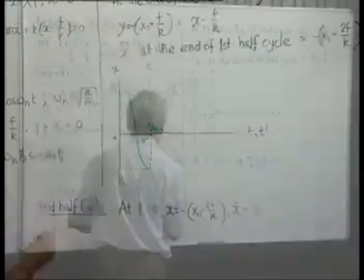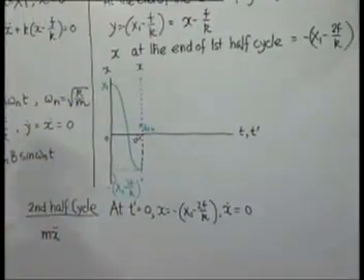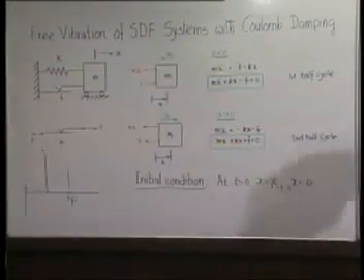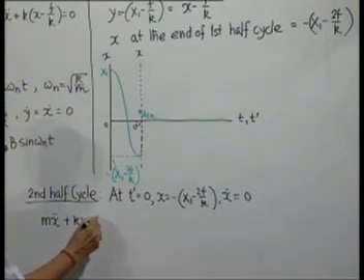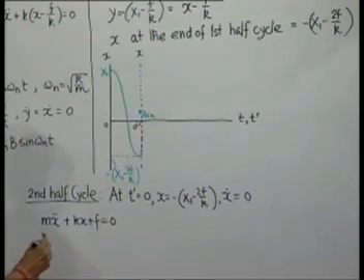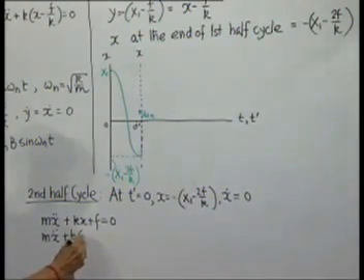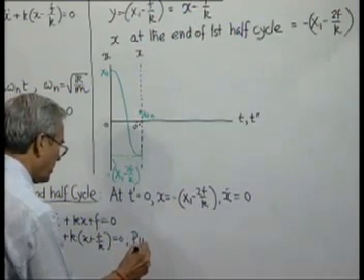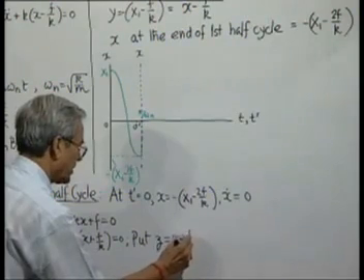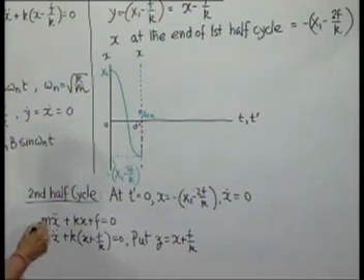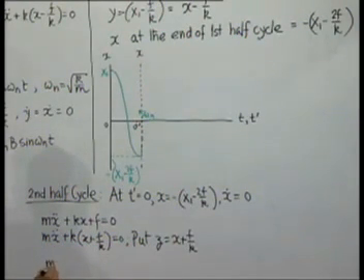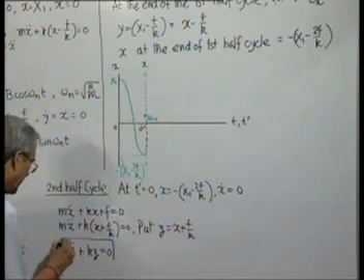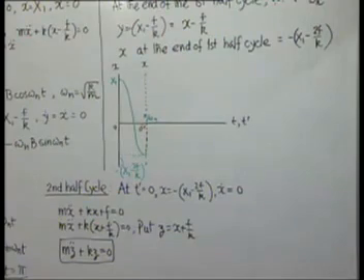We are starting afresh. We start our clock at this time. What is the equation of motion? Now x dot is greater than 0, because now x is increasing and velocity is positive, so this will be the equation of motion. We can rewrite it like this. Put a new variable z equal to x plus f by k. So x2 dot dot will be equal to z2 dot dot plus kz equal to 0. So we get again the same equation with a different variable z now.